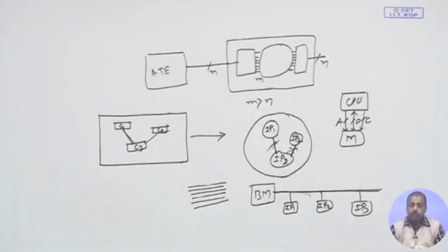So, another problem with bus is that at one point of time only one communication can go through the bus. So, there is a communication bottleneck. I cannot have more than one communication going on simultaneously on a bus. If I have got a hierarchical bus, then to some extent we can have this parallelism, but still if there is a communication across these buses, then one such communication will stall all other communications. So, that way we have got problems with these bus based communication mechanisms.